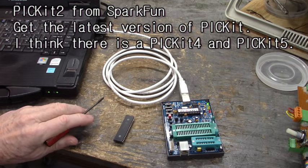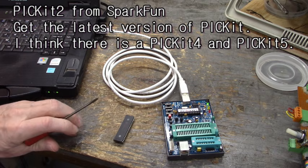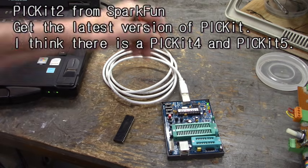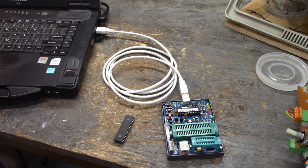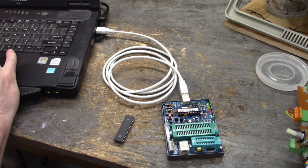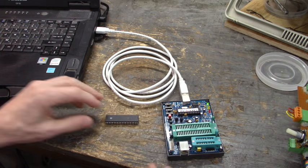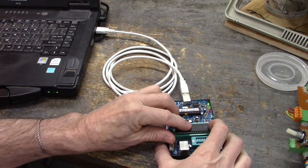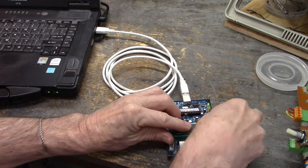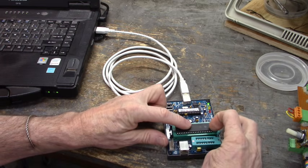This is the PICKit2 from SparkFun. I really like using this. It's not too hard to use. Plugs in with a USB connector right there to the USB port on your computer. And to install your IC into this 40-pin ZIF socket right here. Now pin 1's up here, so make sure the notch is up there.